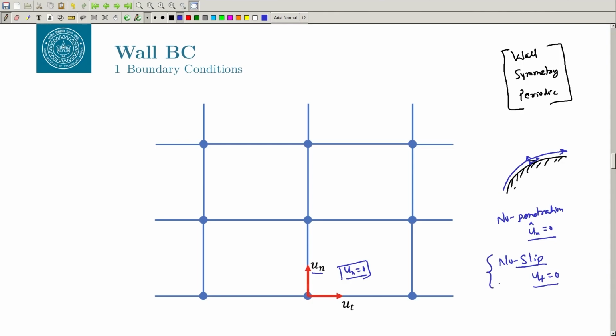But there is also an artificial boundary condition, and it may be physical also at very high Mach number, where the flow is not sticking to the surface. In that case, your ut on the wall will be equal to the free stream velocity, or the velocity on top of the layer. So your ut will become the value, let me call it u, that will be equal to, let us call it, u infinity.